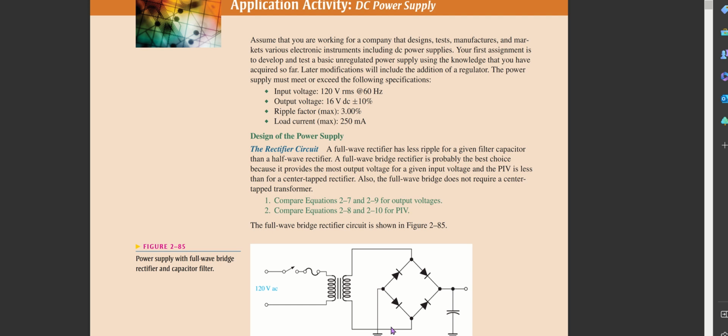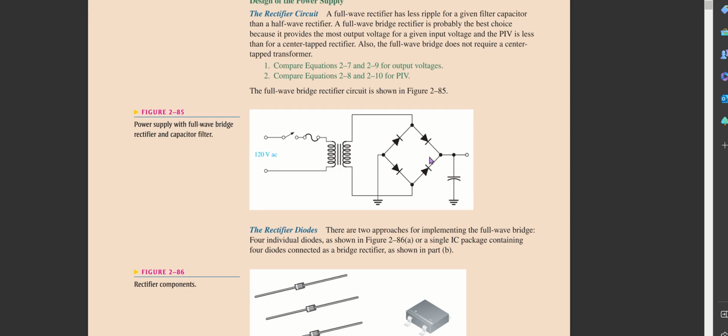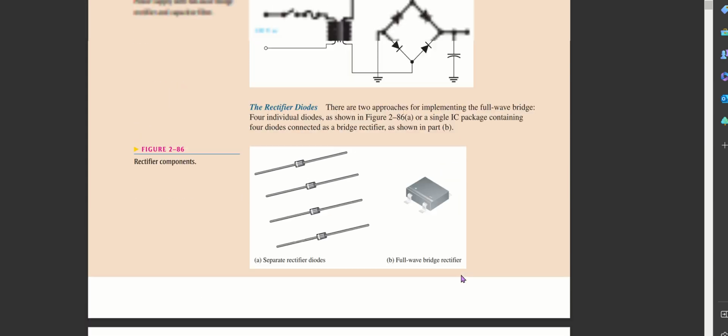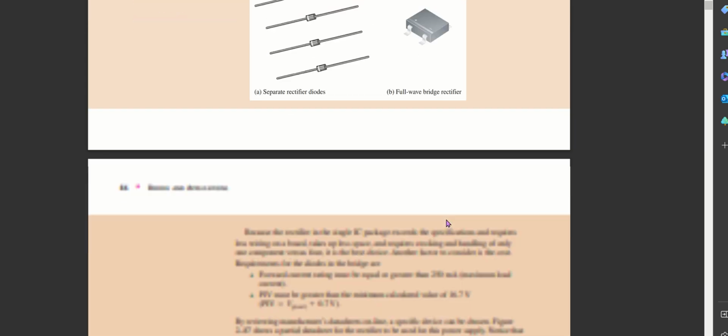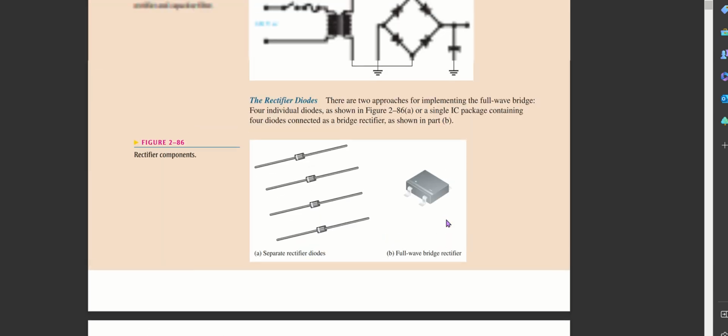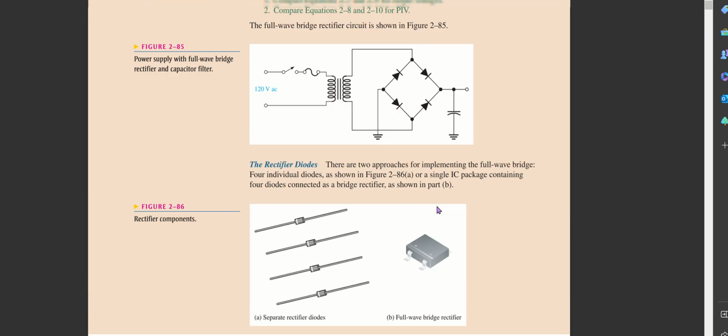Most electronic devices and circuits are powered by a DC power supply. The majority of DC power supplies are in the form of wall adapters, which are used in our homes. So a DC power supply's configuration is like this, and as we can see, we would also be using rectifier diodes. These rectifier diodes form a full wave bridge rectifier, which will be discussed below.